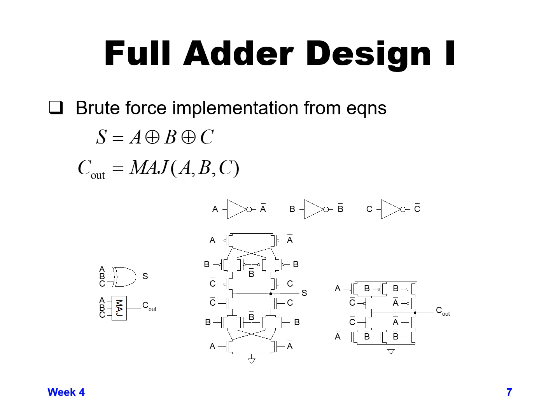If we add up all of the transistors for both of those stages, plus each of the inverters having two transistors each, you'll see that we have 32 transistors needed to implement this entire function. And so we'll look at how that compares versus some other methods to generate sum and carry out.